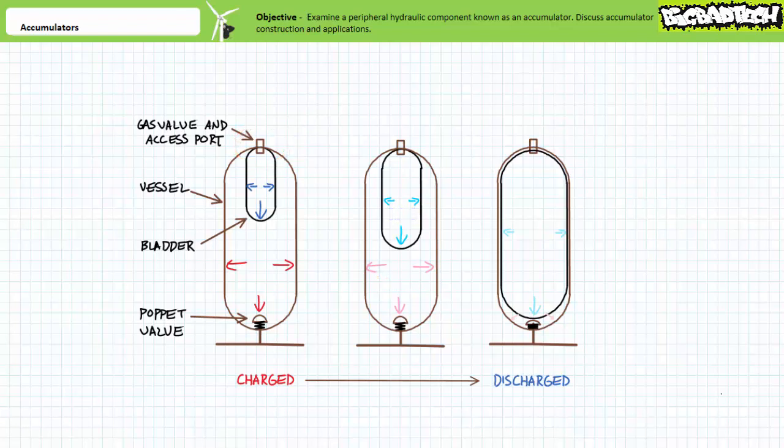Similar to spring-loaded accumulators, all three types of hydro-pneumatic accumulators exert nonlinear force throughout the discharge cycle since they are an interaction between an incompressible liquid and a compressible gas. All three types of gas-charged accumulators necessitate a manufacturer-recommended precharge prior to being used in a hydraulic system. Precharge is the pressure of the compressed gas prior to the admission of fluid.